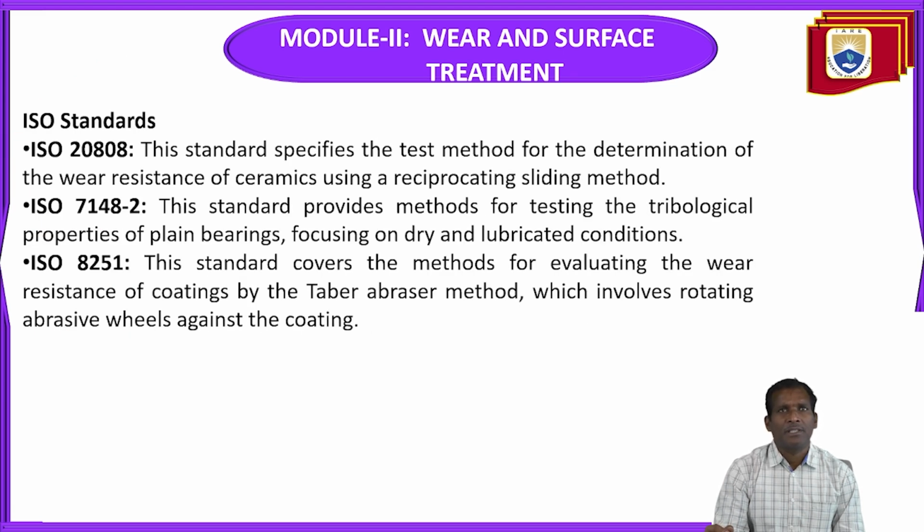And ISO standards. The ISO standards are ISO 20808, ISO 7148-2, and ISO 8251. ISO 20808 specifies the test method for the determination of the wear resistance of ceramics using a reciprocating sliding method.